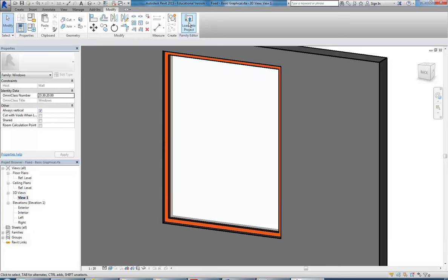Okay, but if I need additional sizes, again, back to Edit Type, then it's a good idea to duplicate this so I can add in multiple types or multiple sizes. So if you don't put any in the family, it'll just give you this name with the same name as your family. So you can duplicate in the project. So I'll do that and I'll make it, what's the size I've already got there? 1000 by 2500.